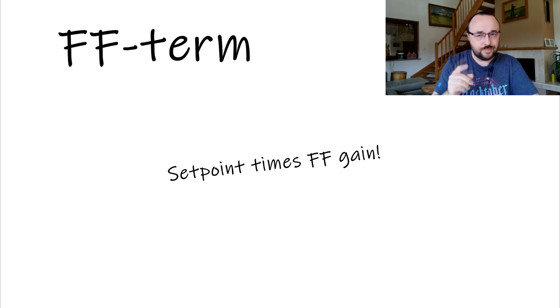Then there is also this feed-forward element. And what's the difference between the feed-forward and all the others? Feed-forward does not take the measurement into consideration at all. It only acts with the set point. We say rotate 100 degrees per second to the right. What it does, just multiplies the 100 by some kind of gain and puts this to the motor. It completely ignores the current state of the system.